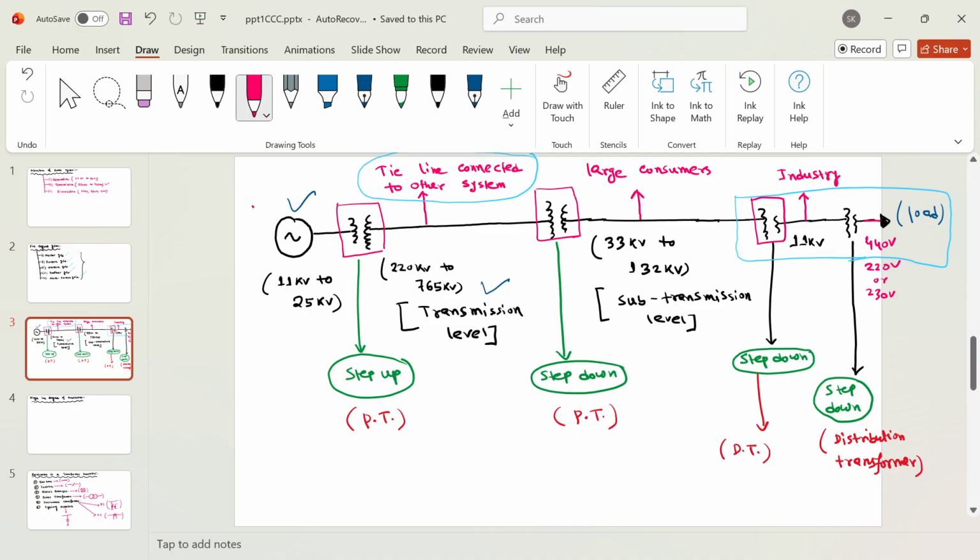If I say what a substation is, a substation is nothing but a place where we make some changes. Maybe we want to change the voltage level. That voltage level change can be done by a transformer substation. Then there can be another substation where we change AC to DC, like we have the HVDC link. We can transform that AC signal to a DC signal in a substation with the help of a rectifier and so on.